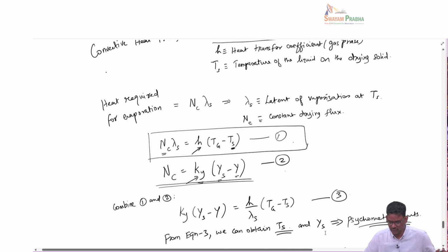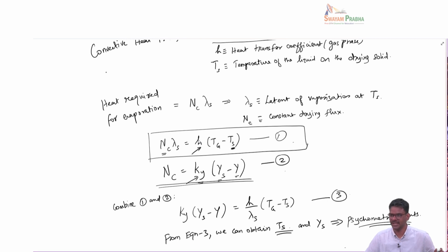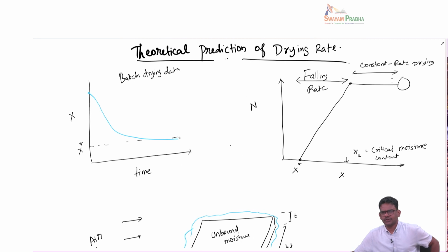Yeah, so basically if you look at this, the temperature sensitivity of the coefficients is not very high, but the driving forces are. Okay, so you could say that if the temperatures change, you can recalculate your coefficients. However, the major component will be the temperature difference being the driving force, which will impact N_C a lot more than the coefficients themselves. Yes. Other things will not change. Yeah, the driving forces are the same. That's a good point.